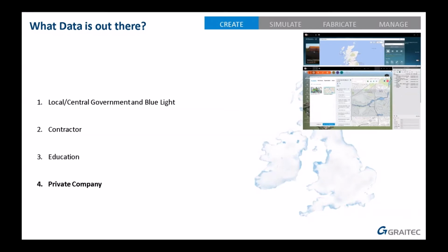Yes, okay. So with the new partnership between Esri and Autodesk, there's some sources available on the ArcGIS server, but I'm not going to advocate this. Be careful here. So the freely published data on the ArcGIS server, so this is your Esri users, all you guys using Esri, the freely published data, there's no guarantee or quality control. There's no documentation. Well, there's limited if there is any at all. Esri UK have published some good data on there, but you'll find loads from students and test data sets and people just messing about. You're best going direct to source on that.